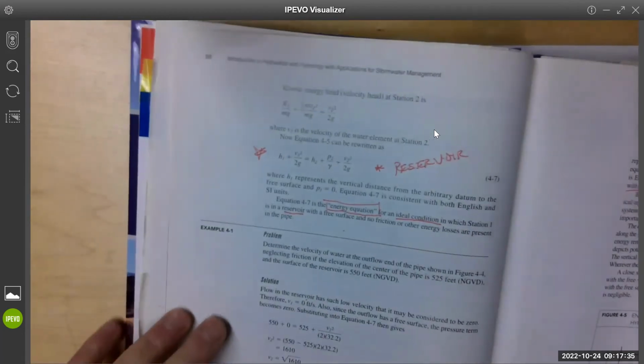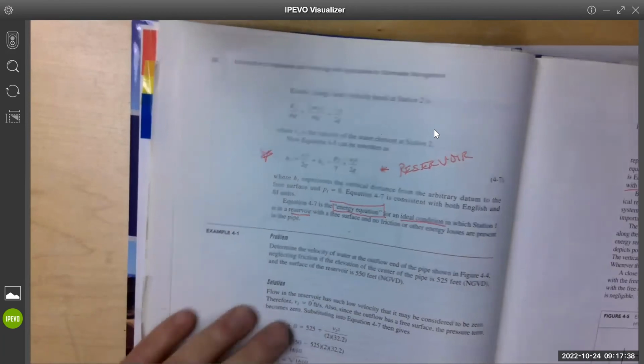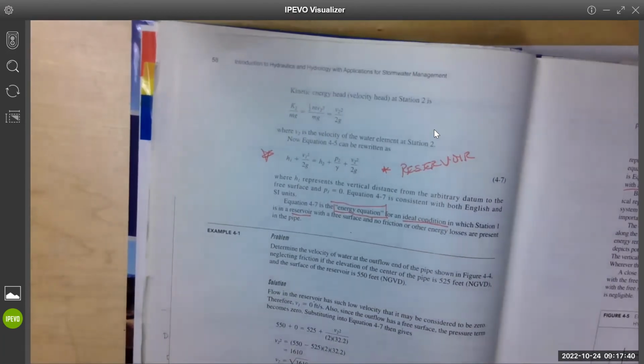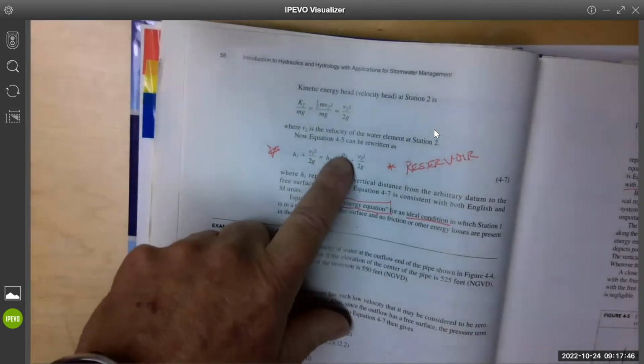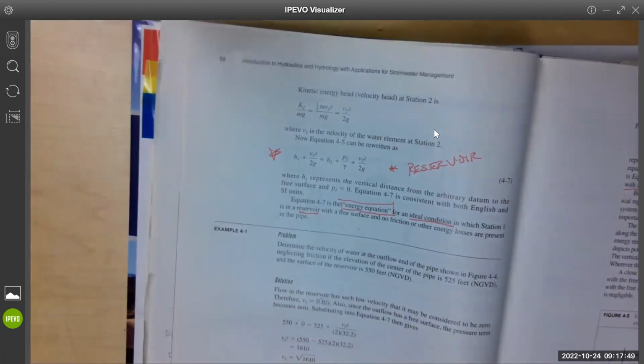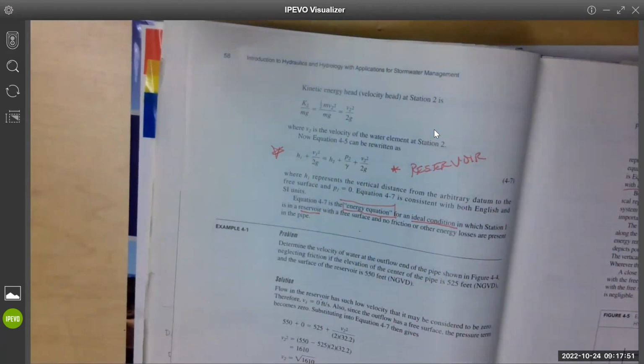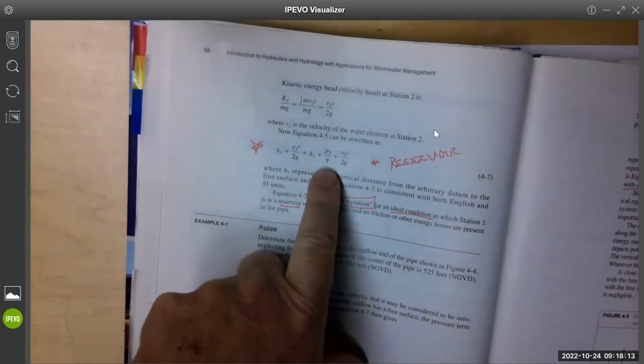All right. So they're pretty simple equations. They all should create the unit of feet, right? So if you take the pressure, give me a unit of pressure. 100 PSI. Yeah, so 100 PSI. Let's use PSF, which is pounds per foot squared, because head's always going to be in feet. We want head to become in feet. So if we have 100 pounds per foot squared, and we divide by the specific weight of the fluid, which is what that equation says.